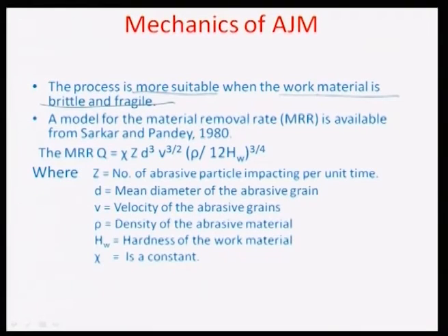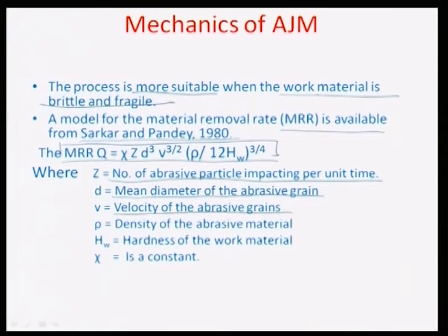And if you look at the various models which are available for estimation of the material removal rates, the most widely used model is that by Sarkar and Pandey, which was formulated in 1980, and this is based on experimental observation, where the MRR or material removal rate is represented by this particular equation here, where Z is the number of abrasive particles impacting per unit time on the surface, D is the mean diameter of the abrasive grains, and velocity of the abrasive grains is V, Rho is the density of the abrasive material, the material of those grains.